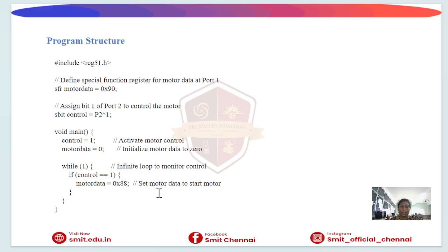This sends the binary pattern to port 1. This is connected to the driver, which energizes the appropriate motor coils, causing the rotor to move. So the complete program working is: initialize the control signal, set motor data to 0, enter the infinite loop, check the control signal, and send the output pattern.